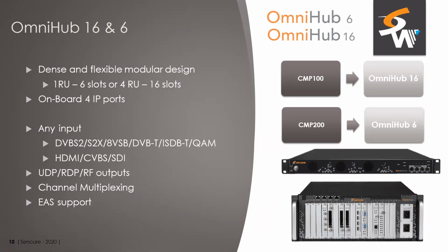Of course, our encoders support MPEG-2 HD, closed captions, AC3 audio. So all mandatory features for the US market. Then we have modulator cards with cable and terrestrial options, which fully support ATSC and DVB standards and related tables. Our portfolio also includes processing modules like the external CI descrambler module for descrambling channels from IP inputs or external inputs, the EAS module to switch input feeds into content received from the emergency alert system, or EIT multiplexing modules, which allow processing EPG data and creating a new EIT table on the output.